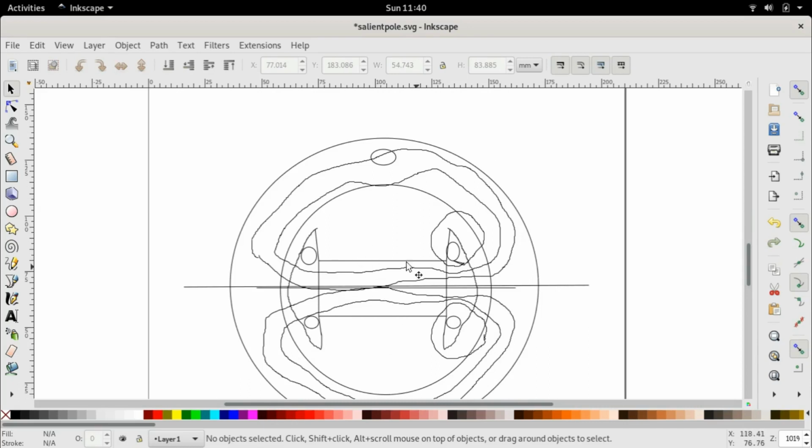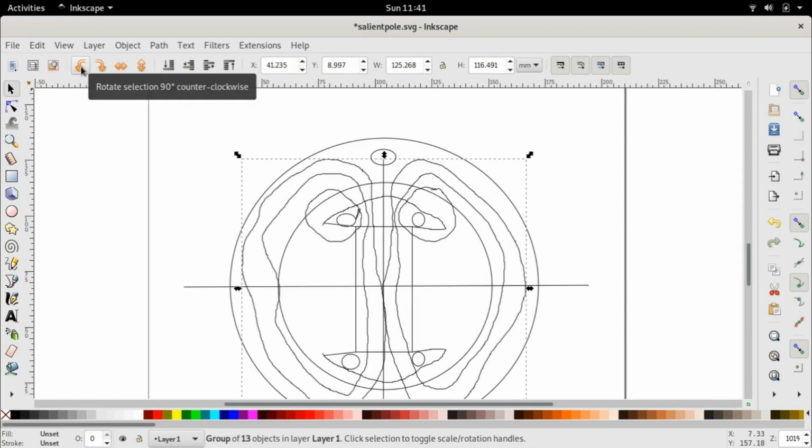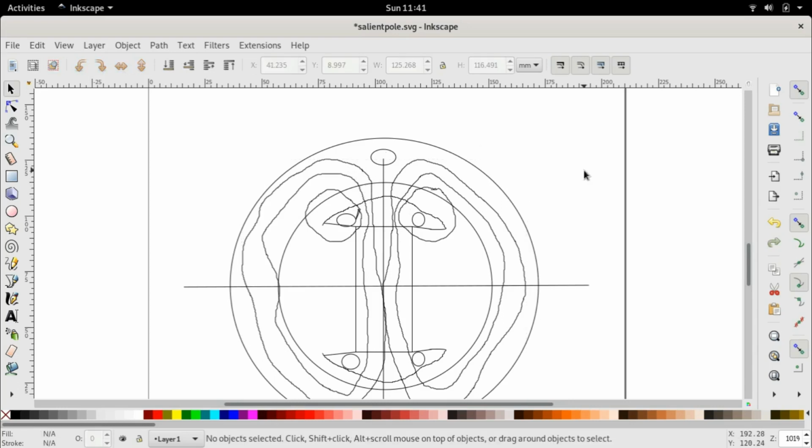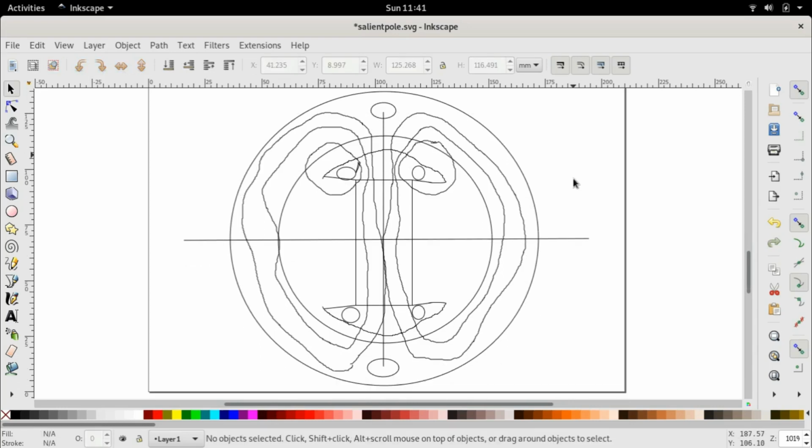And this is something which is very clear once you draw the flux path. You can verify that yourself. You can take a pencil and paper and try to draw it at various different angles, and you will see that the flux path does not change, or rather the length of the air gap does not change, and that automatically means that the flux also does not change.